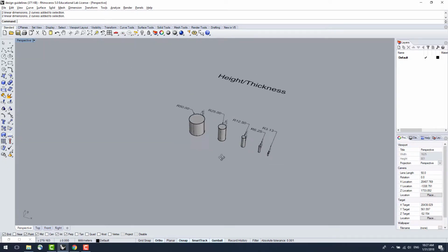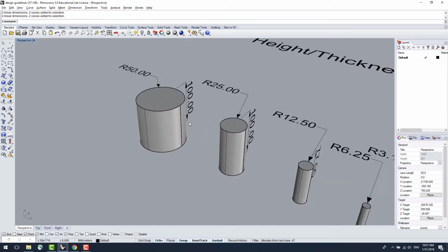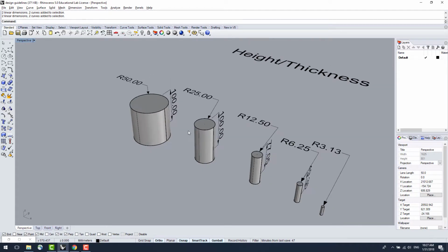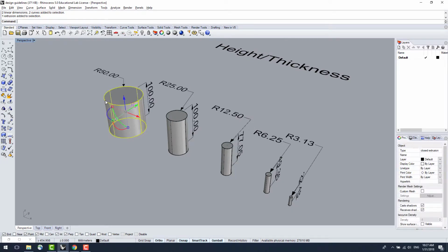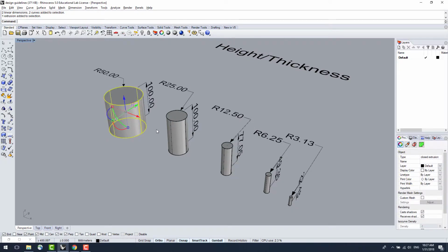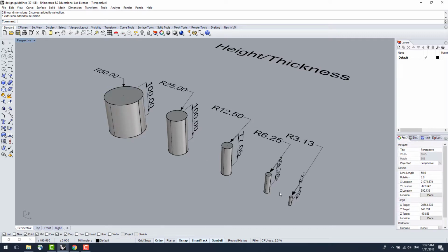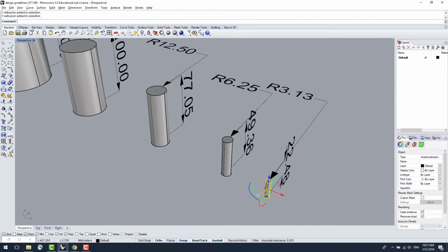Further to this, the taller your geometry is, the thicker it should be to be milled successfully. Geometries of this size are much easier and stronger compared to geometries like this, which are a lot shorter and slender. There are no real measurements about what can or cannot be produced. It's best to talk with the fabricator at FabLab to see.